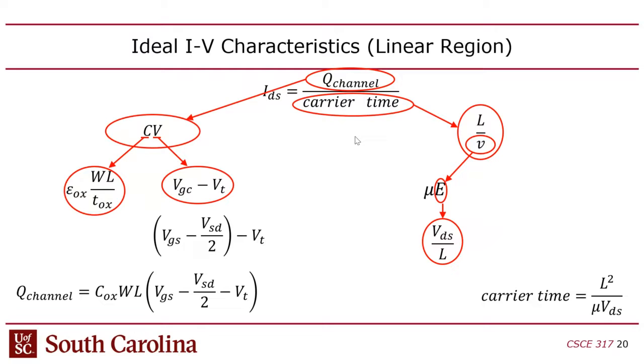So anyway, it's kind of complex how these factors change as you improve the fabrication process. And then, as I mentioned last lecture, you don't have to use the minimum size transistor. If you want more current, you can always scale up the width while leaving the length the same, and you get a linear increase in current as you increase the width.